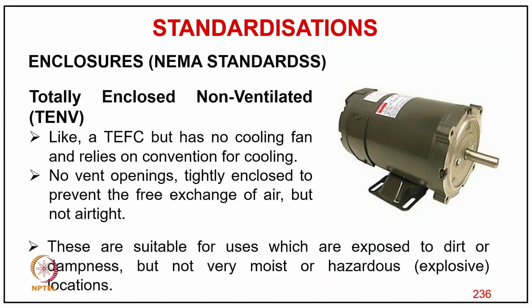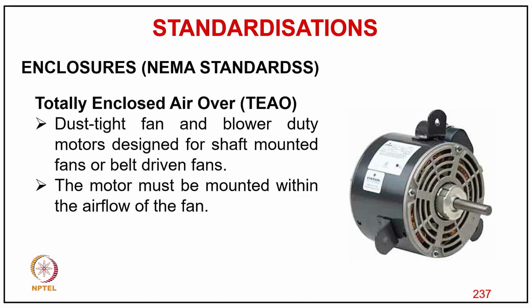Then you have totally enclosed non-ventilated motors, TENV, similar to TEFC but with no cooling fan, and it relies only on convection for cooling, with no vent opening, tightly enclosed to prevent free exchange of air, but not airtight. These are suitable for use where motors are exposed to dirt and dampness, but not much hazardous explosion.